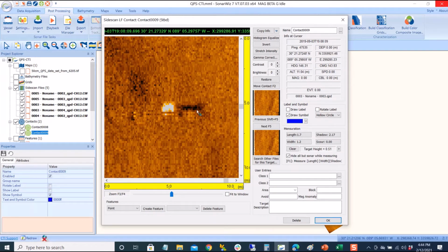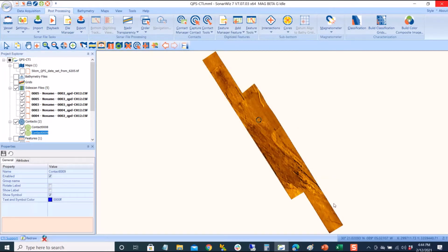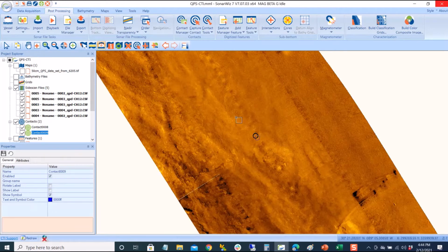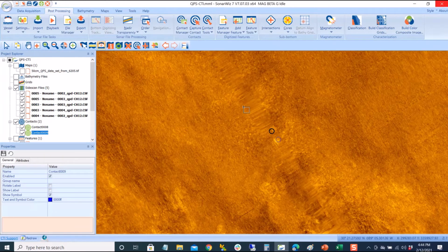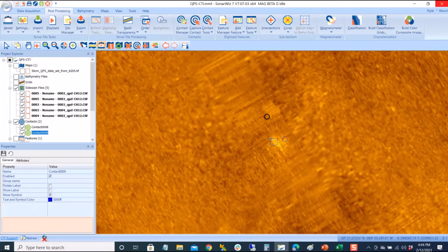So side scan isn't a precise science. It's not like multi-beam. We're going to get close. I had 47 centimeters on the rock height on the first one and 51 centimeters on this one. It's pretty good. But one of the problems we have with side scan is sometimes the position isn't that great. In this case, that's the same rock. It just shifted a little bit.